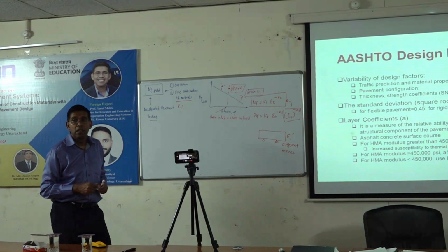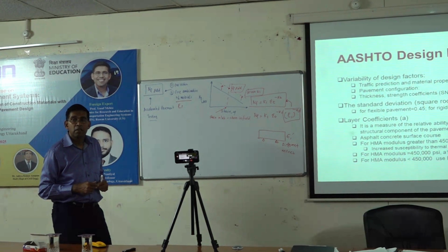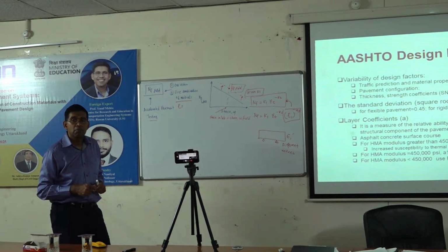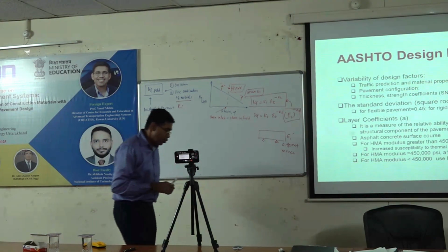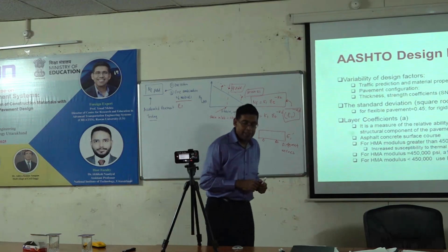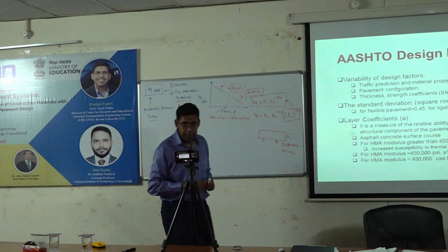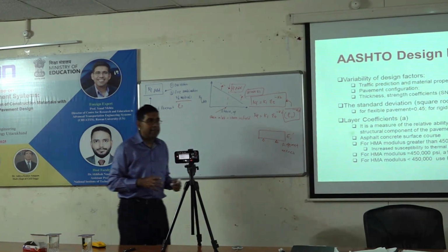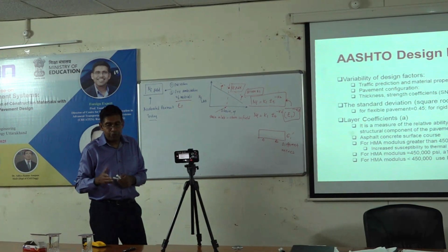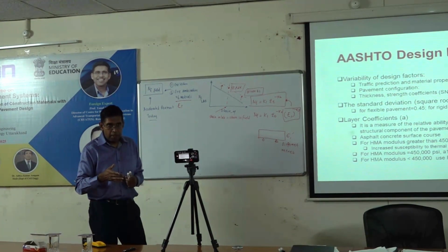The third question is, the final calibrated fatigue distress model was calibrated against certain categories of materials. So if we start using various other materials like SMA, does that calibration factor get affected? Great question. The short answer is yes, it does get affected. The question here is how much you are willing to invest.